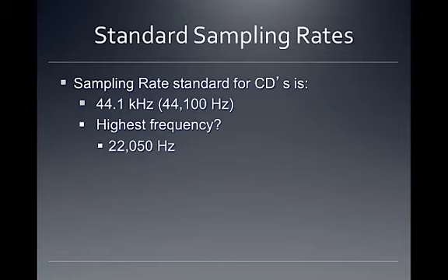So how do we combat that? Well, we combat that with an anti-aliasing filter. A filter, as we know it, would be a high-cut filter in this case, or a low-pass filter. And that thing is set as an input into the digital converter, so that way no frequencies above a certain frequency can even be heard by the digital converter. And this is a great thing, because then if there is audio up in the stratosphere, maybe let's say 24,000 hertz, that is trying to get into that analog to digital converter, the filter just says, nope, you're not getting in there.